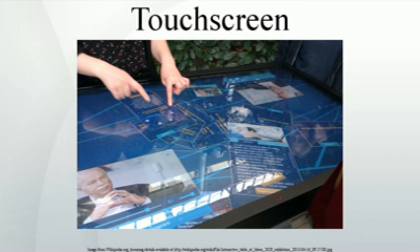Dispersive signal technology, which 3M created in 2002, measures the piezoelectric effect, the voltage generated when mechanical force is applied to a material, that occurs chemically when a strengthened glass substrate is touched. There are 2 infrared-based approaches. In one, an array of sensors detects a finger touching or almost touching the display, thereby interrupting light beams projected over the screen. In the other, bottom-mounted infrared cameras record screen touches. In each case, the system determines the intended command based on the controls showing on the screen at the time and the location of the touch.